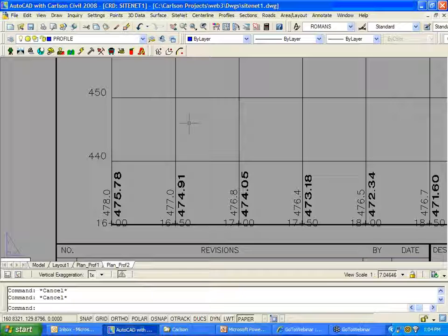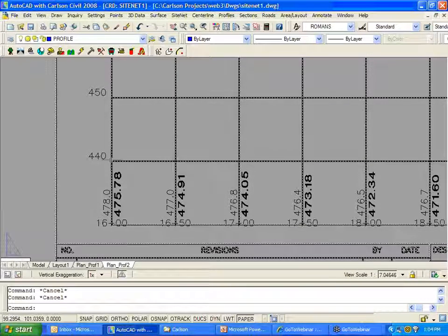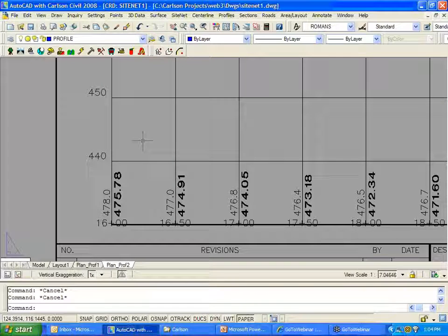So basically, what you would do is open up that title block drawing and see where 0, 0 is. Then another option, which I've honestly not tried, but now I'm going to go try, is to maybe leave 0, 0 and move the base point, BASE, and see if that triggers this correctly. That might be another solution. So that's an interesting question. I'm going to experiment with that myself.